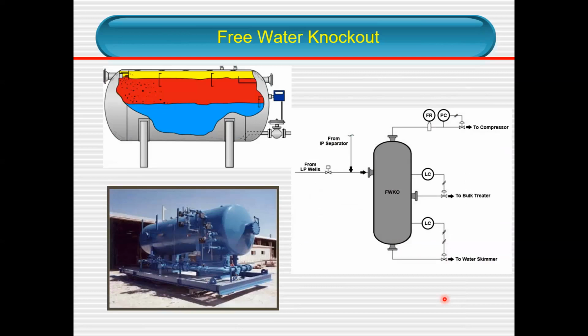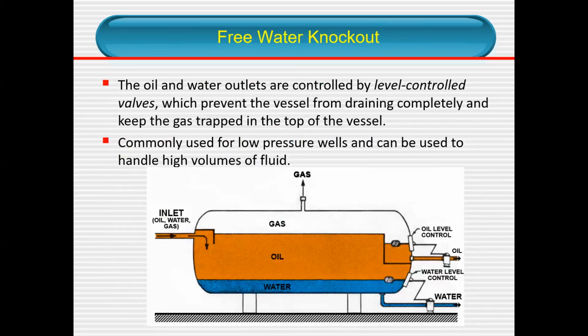Most of the time, not all the time, they will be using chemicals as well to make sure that the water is totally free of contaminants. The oil-in-water content is another factor. If I'm not mistaken, if the oil is lower than 40 parts per million, it is okay to throw overboard. If it is more than that, you cannot. You have to treat it again until it is below 40 ppm.